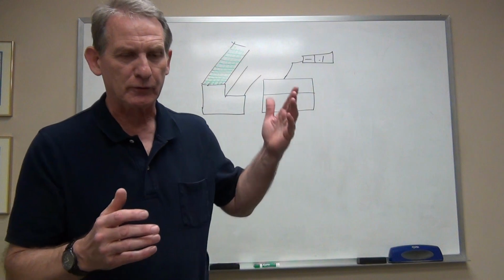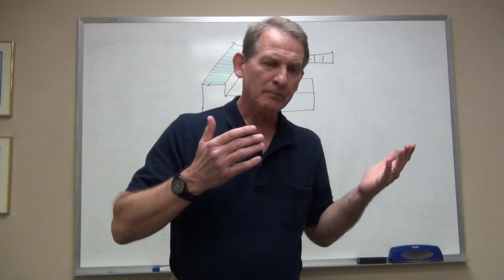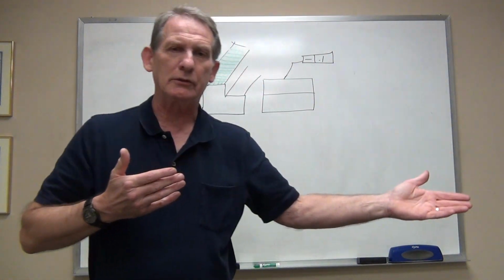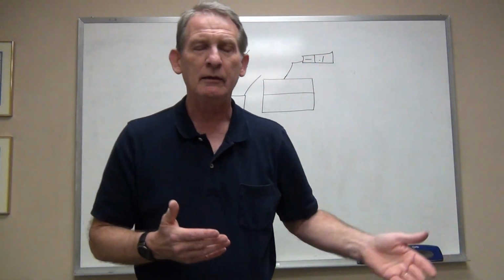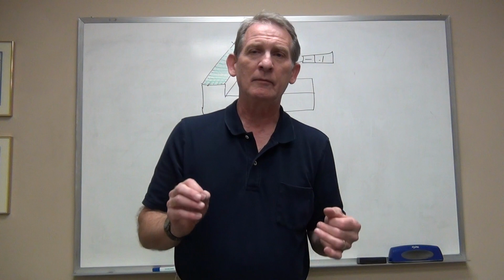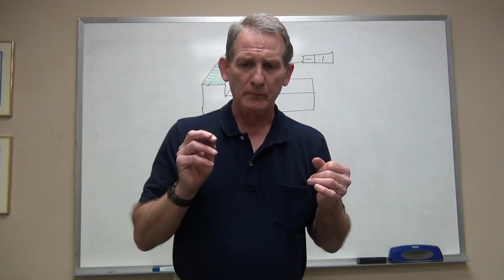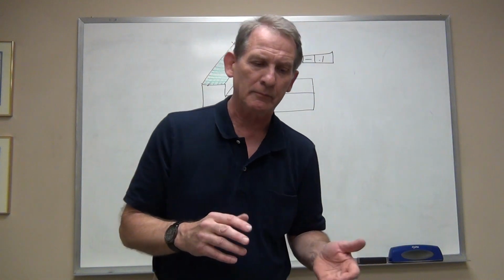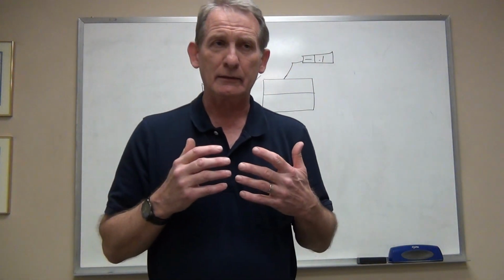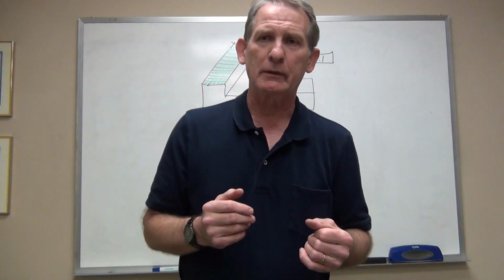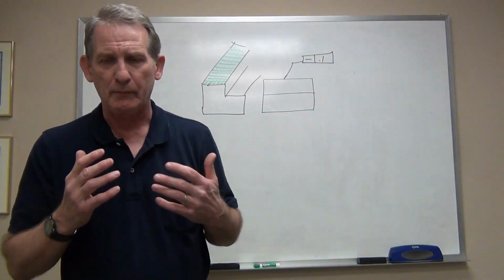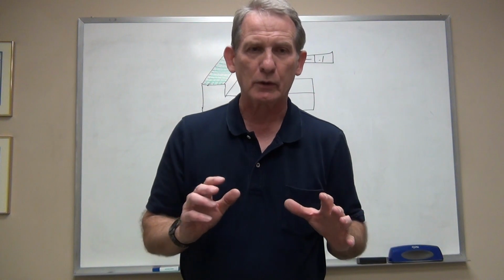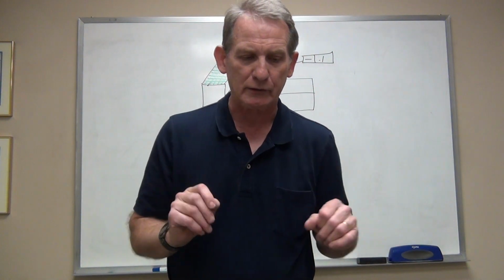Now, flatness versus straightness, again, this is in the realm of pure geometry, where straightness is a comparison to a geometric line. Flatness is going to be a comparison of a feature to a geometric plane. Again, flatness is a super critical requirement in all precision measurement and machining. All these aspects rely on some flatness basis.